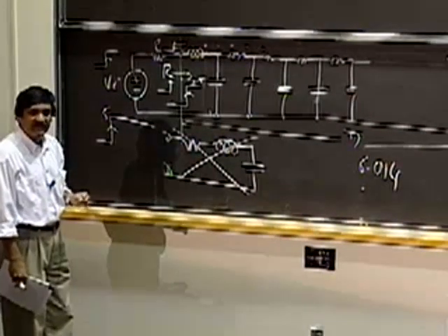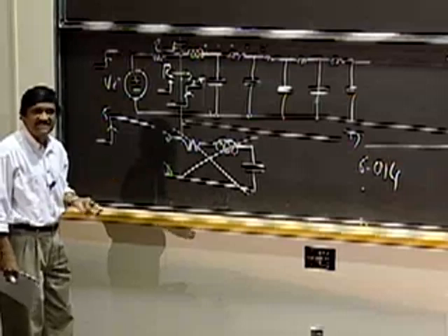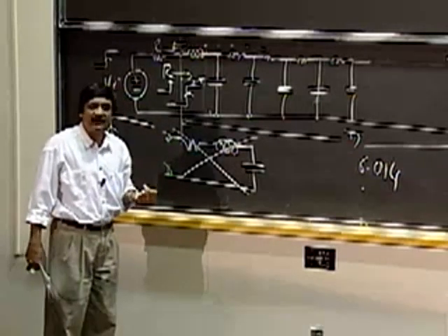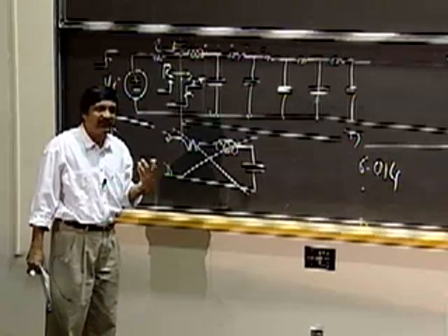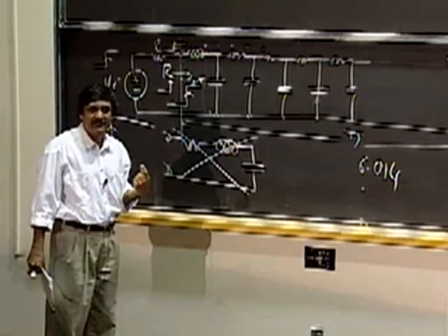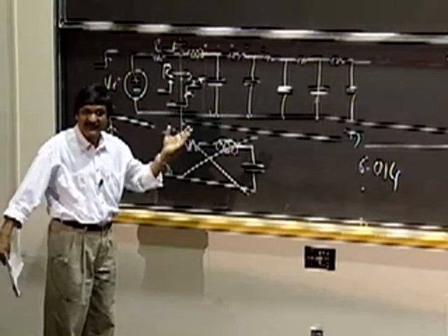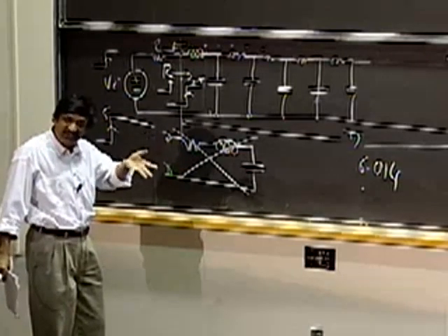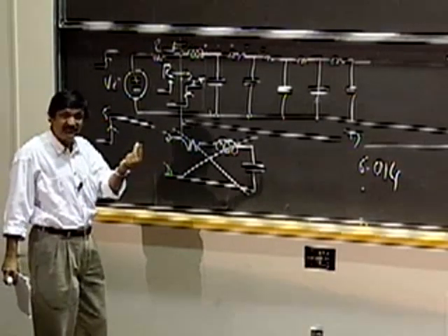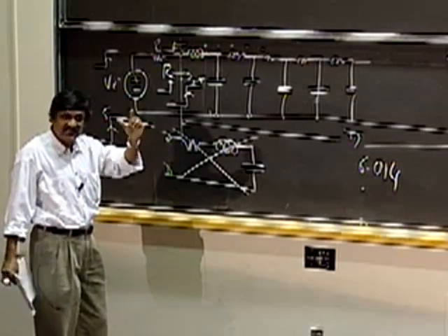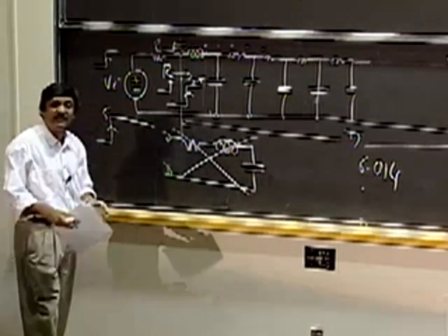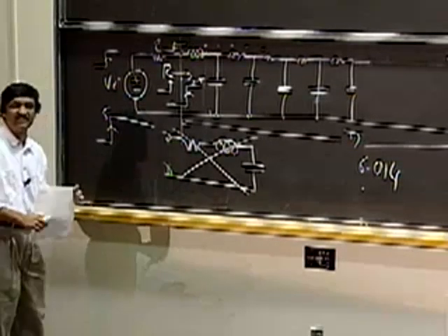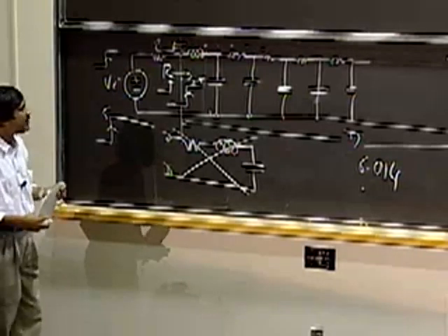If you want to design multi-gigahertz chips, it turns out that if you have signals traveling around at edge speeds in the 0.1 to 1 nanosecond range, remember, light travels roughly 1 nanosecond a foot. And if the signals of interest are 0.1 nanoseconds, then if your chips are 1 inch in size, the propagation time of a signal across the chip is 0.1 nanoseconds. So today we have to deal with these issues and try to figure out what to do about them.